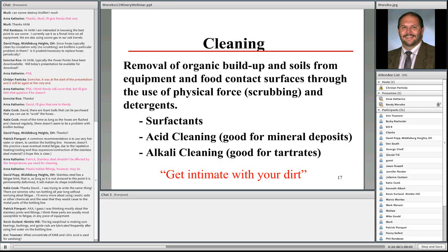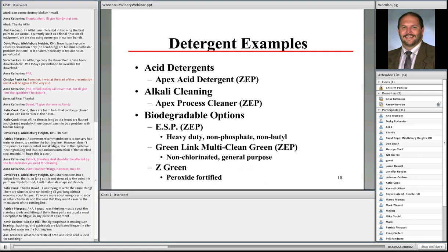I would suggest using alkali 4 out of the 5 days for a facility, or 4 out of 5 cleanings should be alkali, and then that 1 out of 5 can be an acid cleaner, which will remove the deposits that are not lifted off by normal alkali treatments.